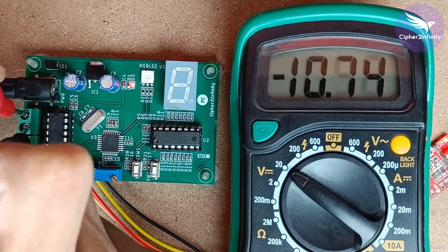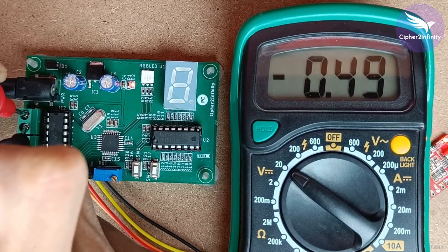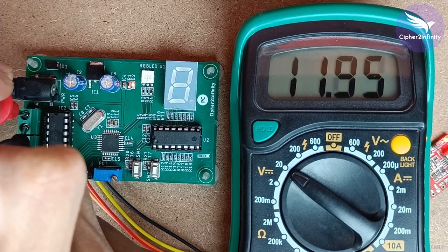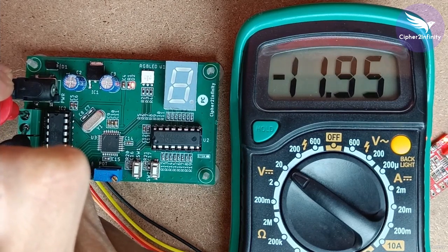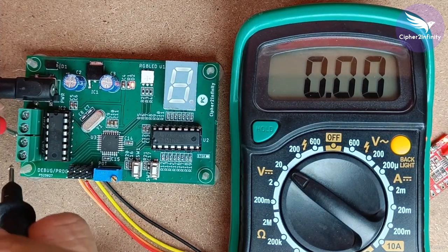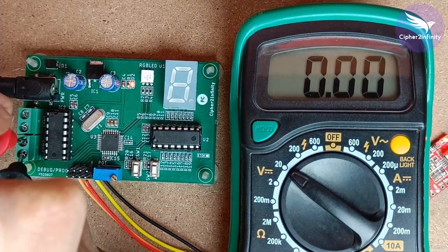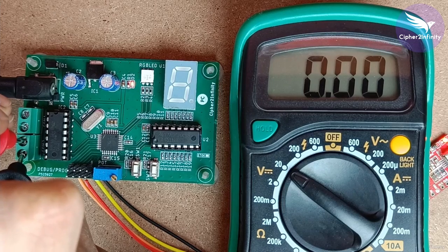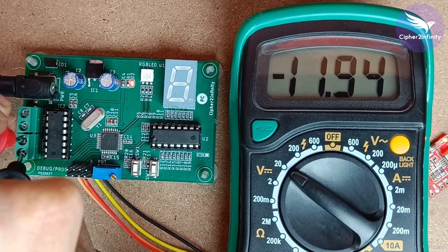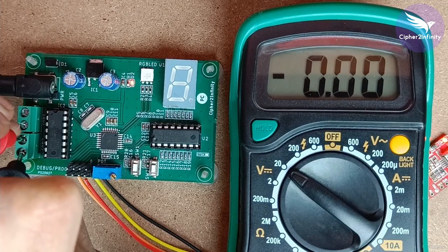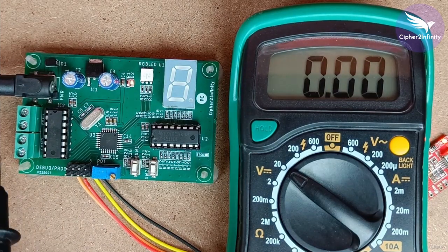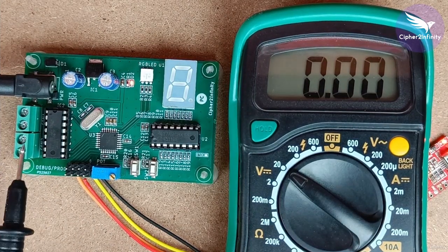Okay, so this actually ensures that everything is perfectly fine with channel 1 or connector 1. Initially we are getting plus 12 volt, and later you can see the polarity is changing to minus 12 volt. In the same way you have to do it for the second terminal. Right now you can see we are getting 11.95 or plus 12 volt, and later you are getting the negative or minus 12 volt. This is how you can verify whether the L293D section is working properly or not.